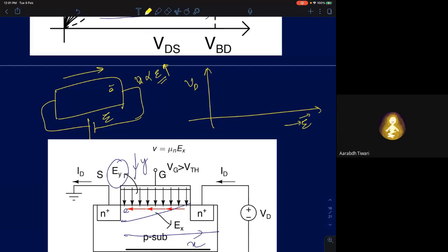That won't contribute to an increase in the electron's energy. There is a minimum distance an electron travels before collision. If the electric field becomes so high, the electrons will undergo so many collisions that the electric field will no longer be able to build up the velocity. Any excess energy is absorbed by the lattice and dissipated as heat.